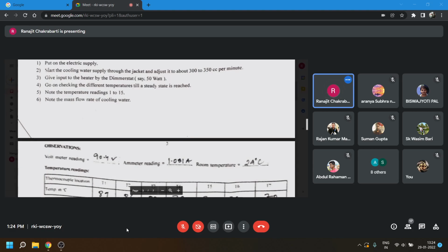The other end is kept at a lower temperature. The direction of heat transfer is along the length of the rod. Other directions of heat transfer are not existing. We are assuming that the temperature gradient is only along the length of the rod, not along the radius, not along any angular direction. The heat transfer occurs only along the length of the rod. So this is a one-dimensional heat conduction.